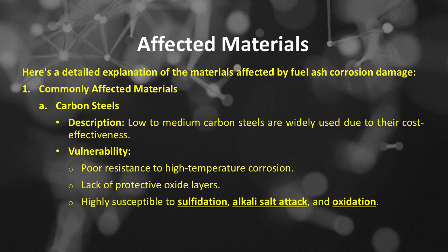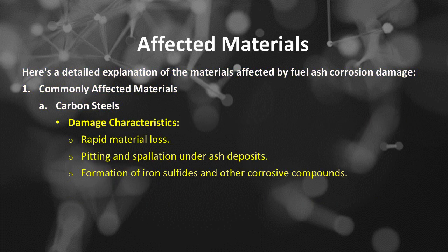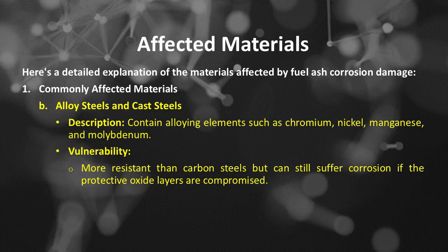Number A: carbon steels. Description: low to medium carbon steels are widely used due to their cost-effectiveness. Vulnerability includes poor resistance to high-temperature corrosion, lack of protective oxide layers, highly susceptible to sulfidation, alkali salt attack, and oxidation. Carbon steel's damage characteristics include rapid material loss, pitting and spallation under ash deposits, and formation of iron sulfides and other corrosive compounds.